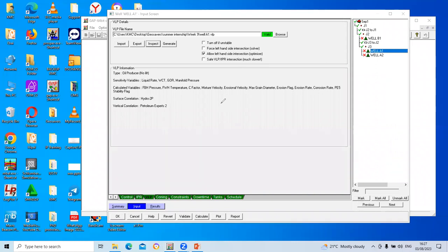We may have our VLP that looks like that. We may have our gas oil ratio. We may have our IPR that looks like that. So you realize that our system performance is surely at the point of intersection of the vertical lift performance and the inflow performance relation. But in this case, we have two intersections. So we have to choose which of them is the best value for that system. So if you look at it, you will now see what you have to choose from here.